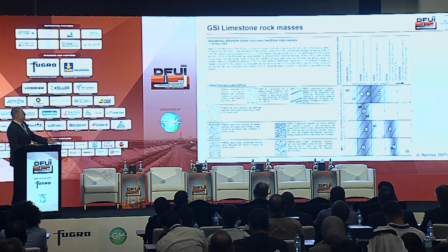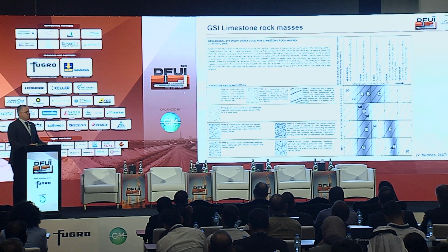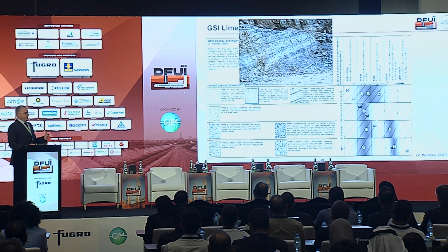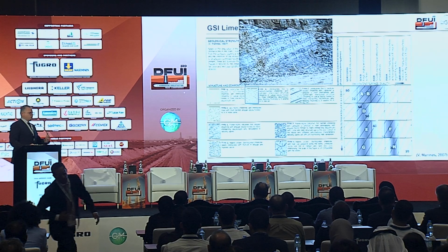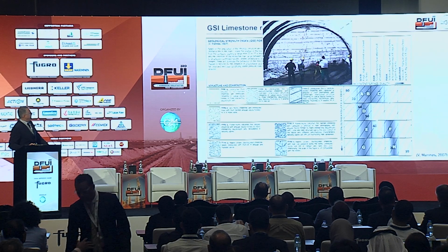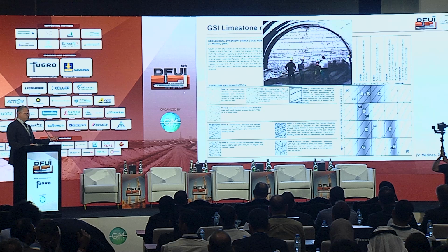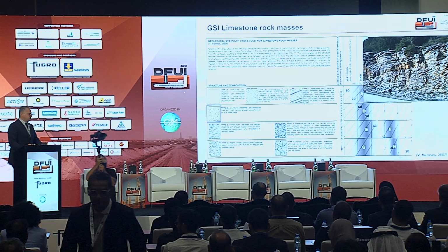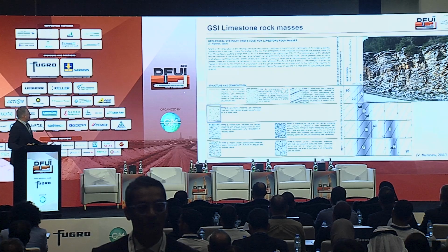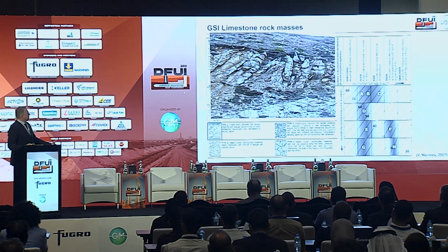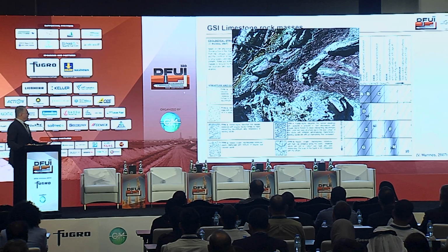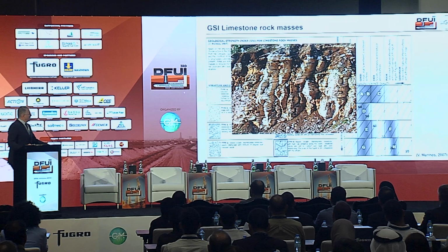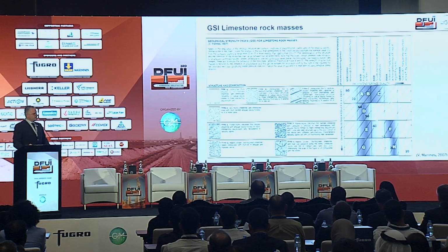At the same time, here you see different kinds of rock mass types in limestone rock mass. You see different rock mass types that can have, of course, alternations with other weaker, softer material, but not so tectonically disturbed, which we are very happy about, but then it becomes more fractured or more folded, with or without intercalations, or very fractured, or with high infillings.